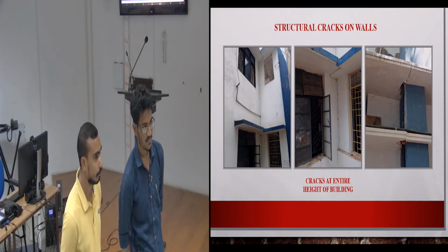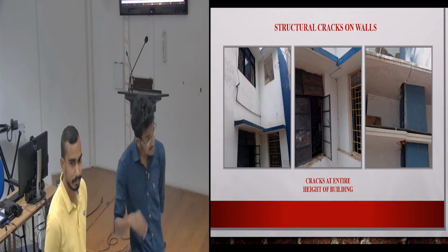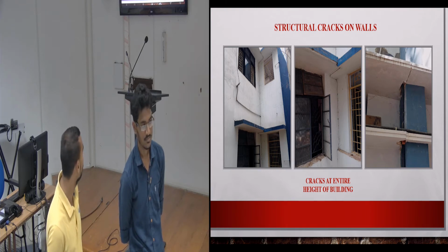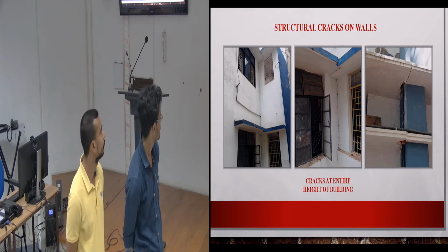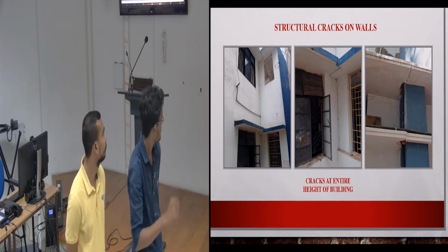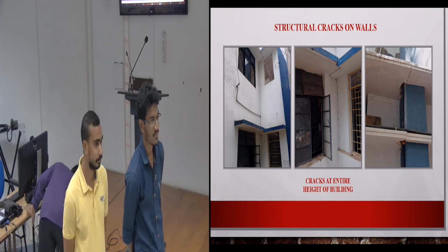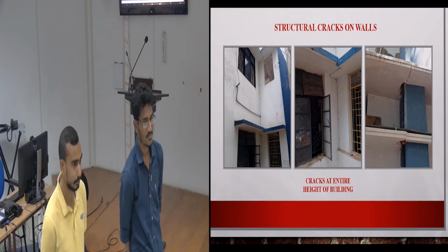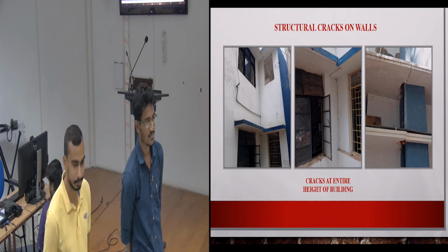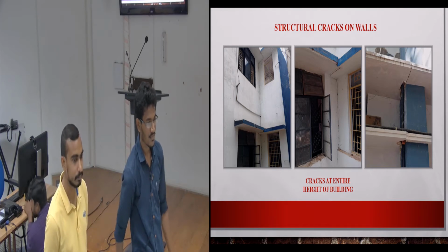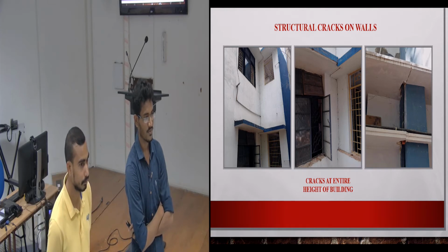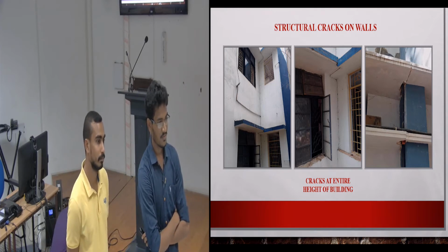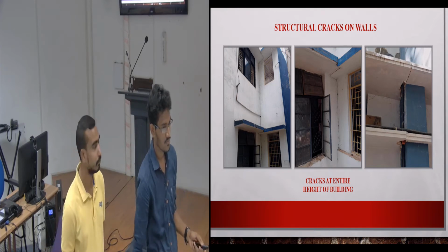If they would have gone for 1.5 or 2 meters deep, and this was 1.75, some sort of difference, because I can see there are no other cracks other than the joints between the old building and the new building connection. So this is the tricky part. It should be an interaction of the foundation with the temperature effect. I agree. There should be a coupling of foundation failure and then maybe some thermal effect. But then you should check below.